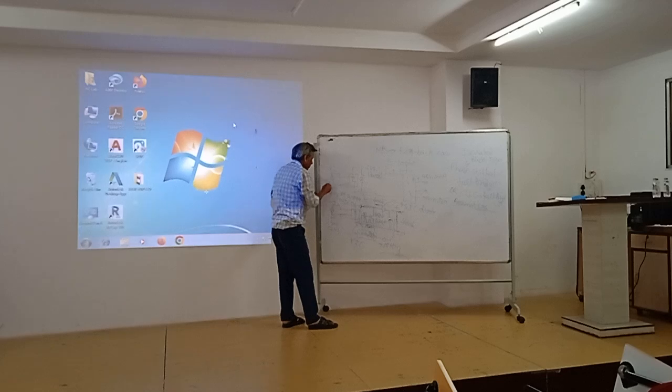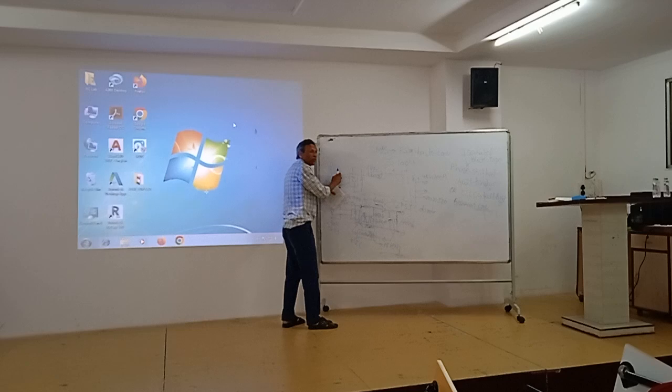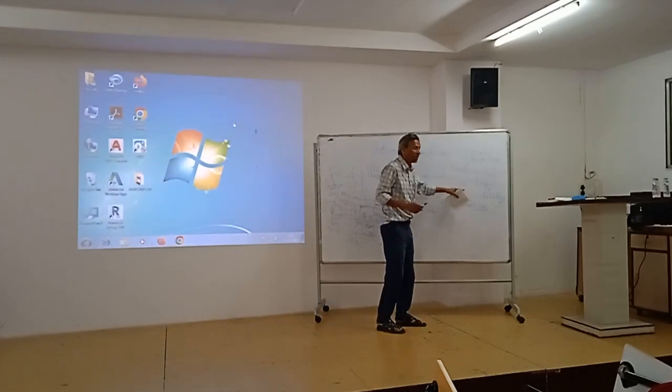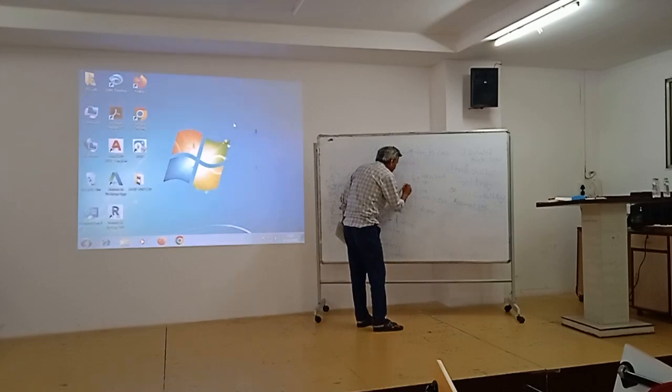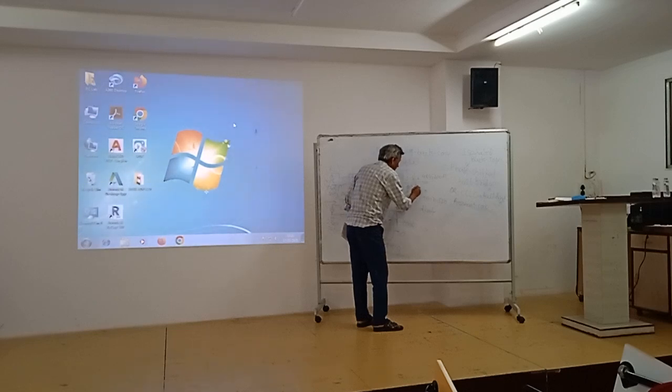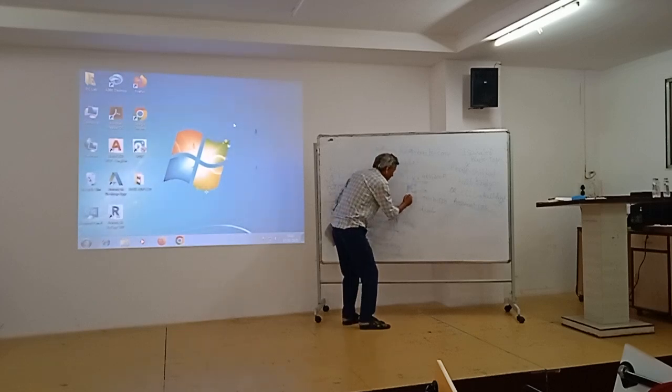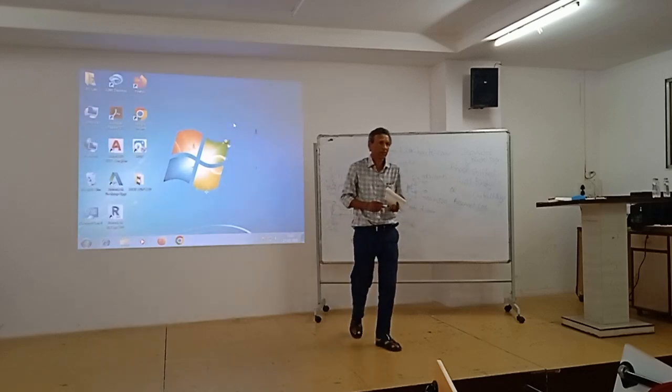And anyway, here between the load, see here there is no isolation. So this is phase and neutral. Now you know, sometimes this neutral is shorted to phase. It is happening. So instead of 230, suddenly 430 will come, 460 will come. It will damage everything. So here somehow you have to have an isolation. And this isolation in phase shifted full bridge will be achieved through the HF transformer.